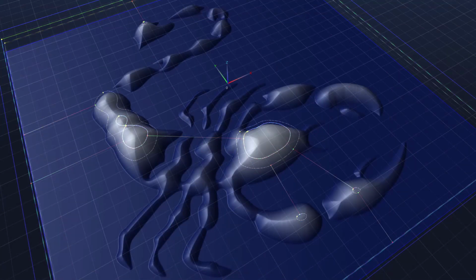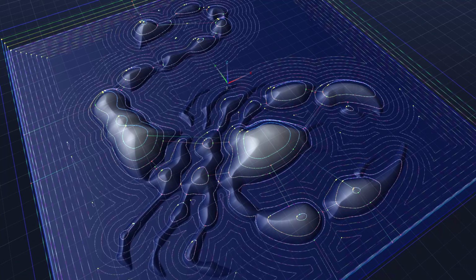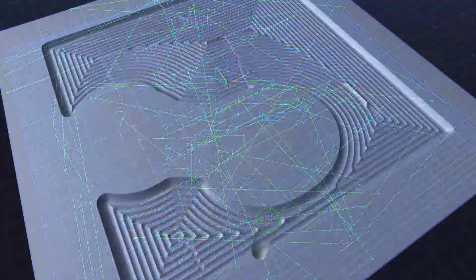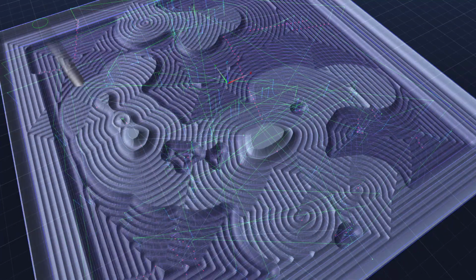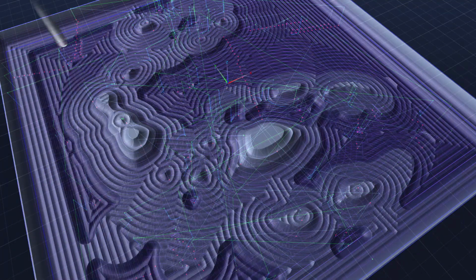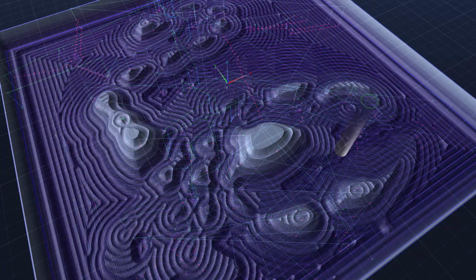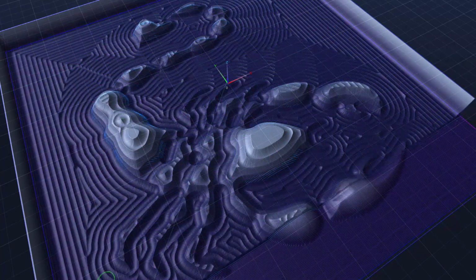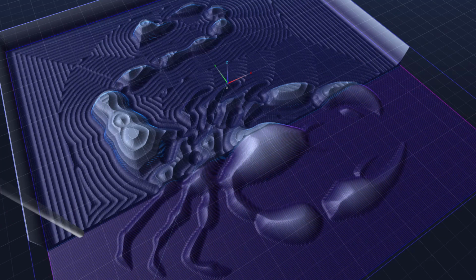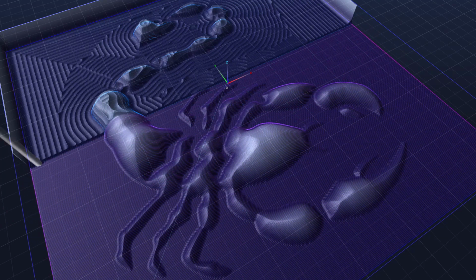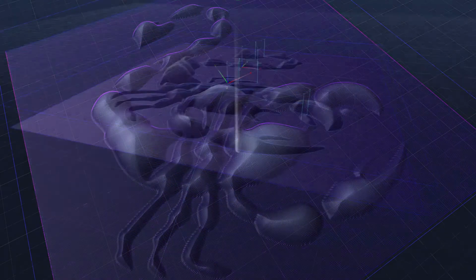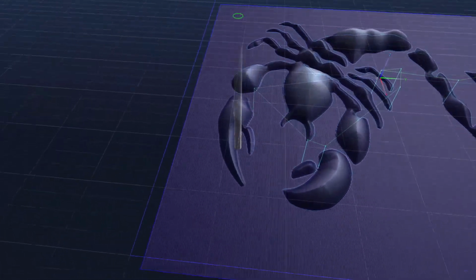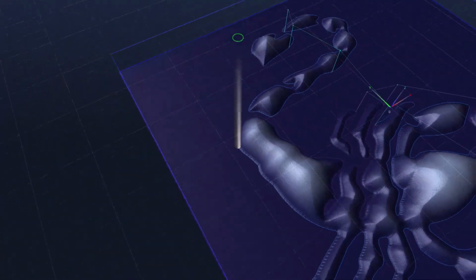All right, so that's it for this video. We've gone over tracing paths. We generated some strokes along those paths, which generates a raster layer that we can then composite into our project. We also generated shapes from closed paths using the shapes from paths function. And I showed you guys how to edit path layers as well. And then we finished off with generating some path sweeps, designating a rail path and some profile paths to do a single rail path sweep, as well as designating 2 paths as rails to use for a double rail sweep.